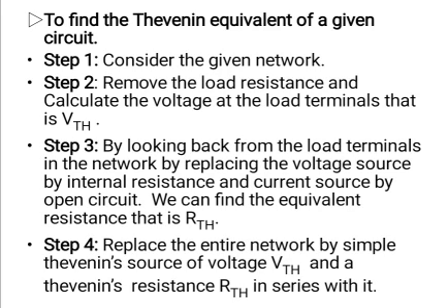Step 4, replace the entire network by a simple Thevenin source of voltage VTH and a Thevenin's resistance RTH connected in series with it.